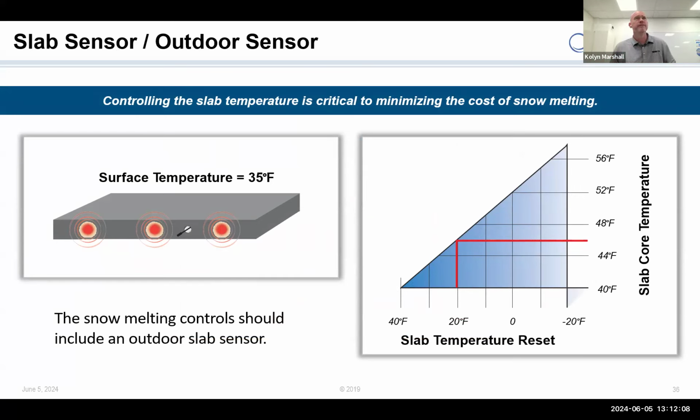Variable speed mixing systems allow me to have variable temperatures, so that when it gets colder, it automatically ramps up the temperature to the system. So I get my more constant, more steady response out of the system.